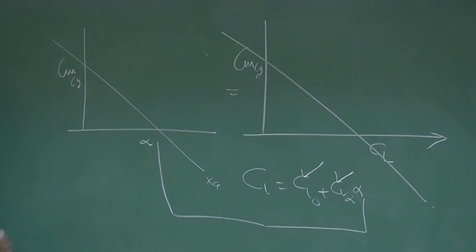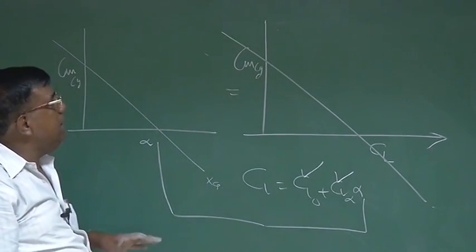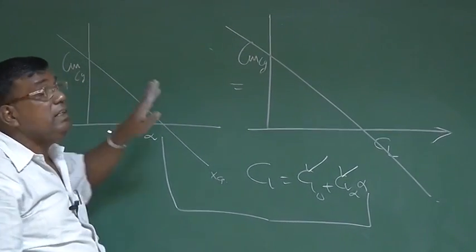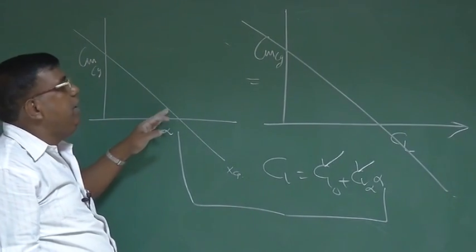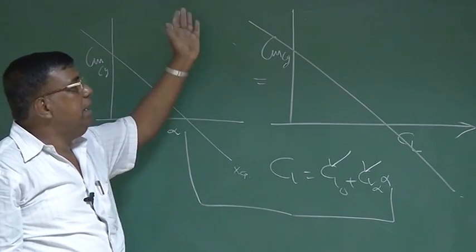Now if the variation of Cm and Cl is like this, let us see what the equilibrium point is. Please understand, from the Cm versus alpha graph, I am now shifting towards the Cm versus Cl graph. For each alpha there is a corresponding Cl, so I will be replacing alpha by Cl. So let's say that is the graph.